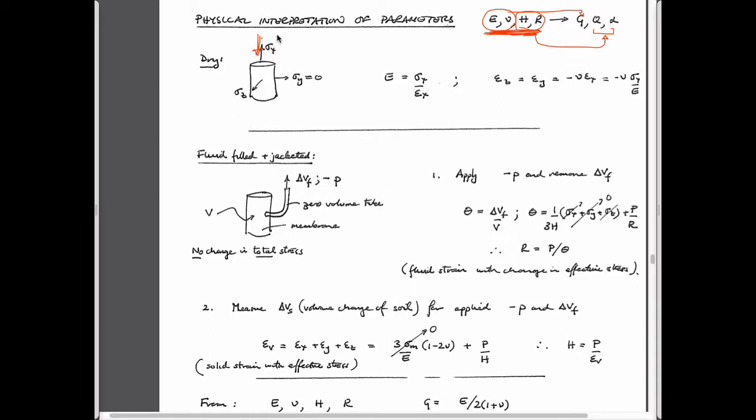So you apply a stress in this direction. If there's no change in stresses in the horizontal direction, if we set these equal to 0 and don't allow them to change, then the strain that we get in the x direction is given by the stress divided by modulus. This is just Hooke's law written in its simplest way.